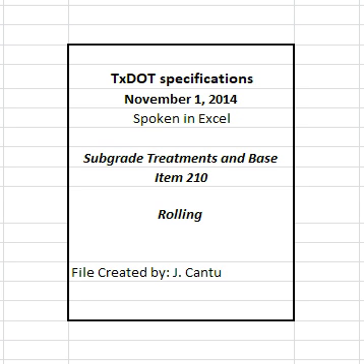For asphalt stabilized base and asphalt concrete pavement, furnish a roller that also has the ability to automatically reverse the direction of the rotating eccentric weight.